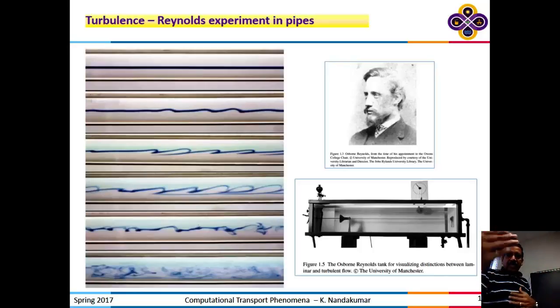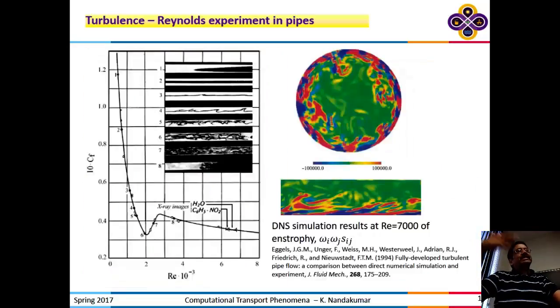And this is a classic Reynolds experiment to illustrate, and he discovered, of course, the dimensionless number. If you put them in dimensionless form, the transition seems to occur somewhere about 2100, but it can be pushed all the way to 100,000. That we knew only recently, after many failed attempts to predict that critical value.